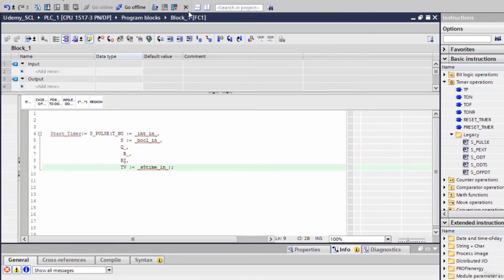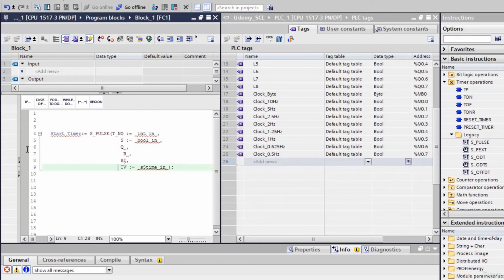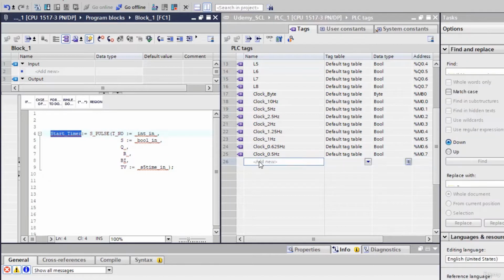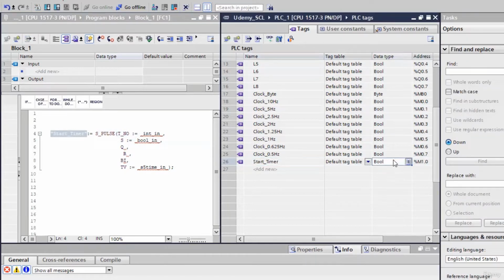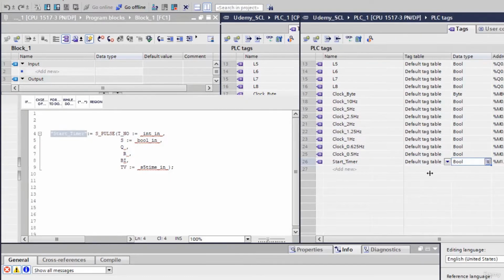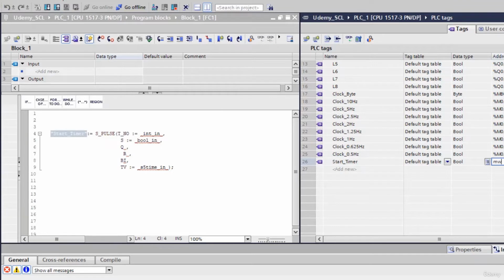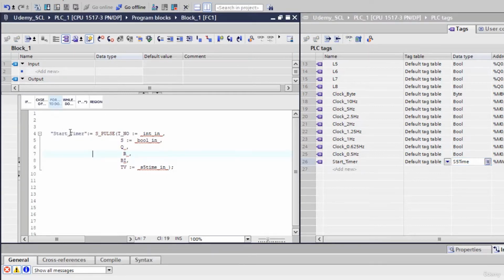You should remember here what your requirement of the tag is. Okay, so I have defined one start timer here. So what I will do, I will paste here start timer, and I will change the type of my data type. I will put S5 time, and I will write here MW20. Okay, I will write S5 time. As soon as I write S5 time and data type MW20, okay, this start timer converts into OK, meaning the red line is removed. Now here there is a timer number.